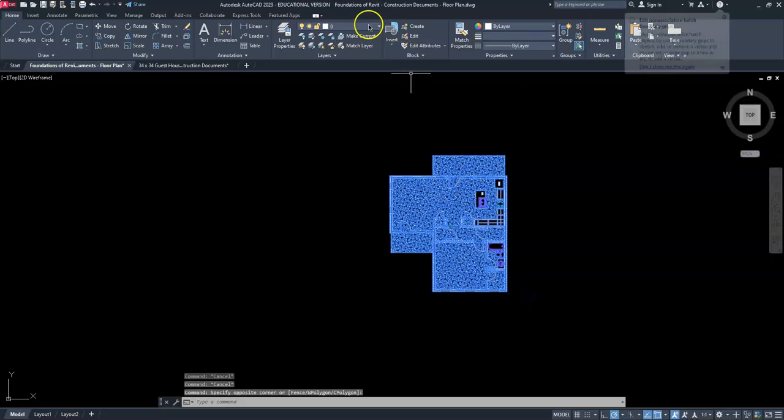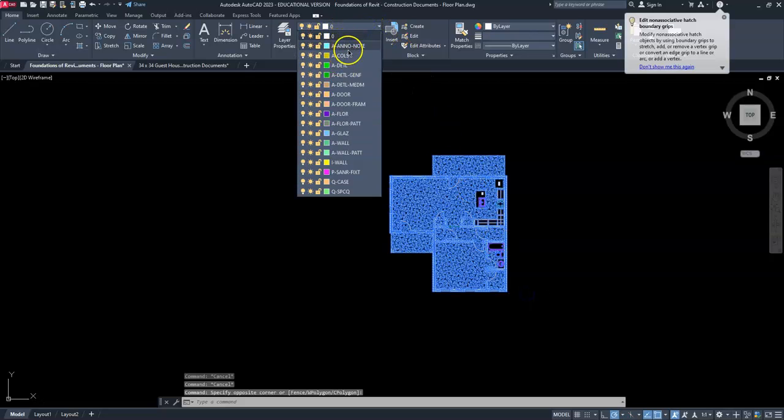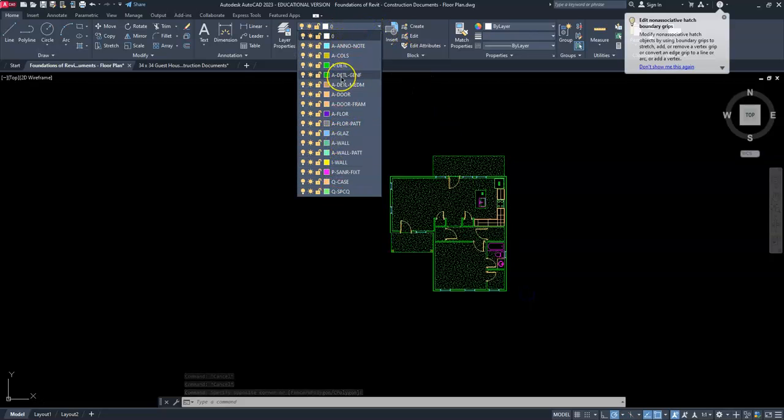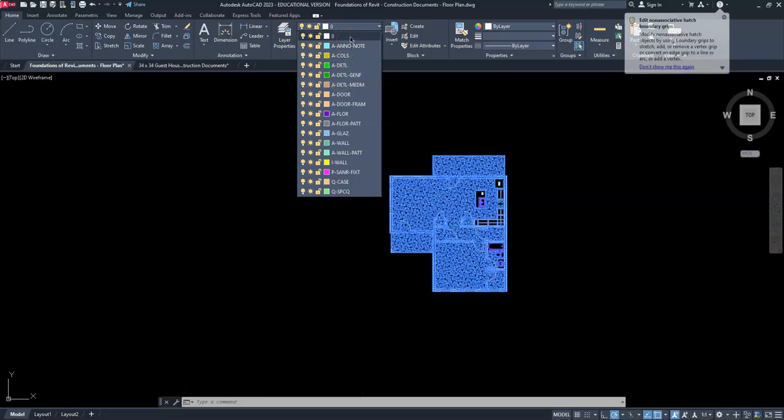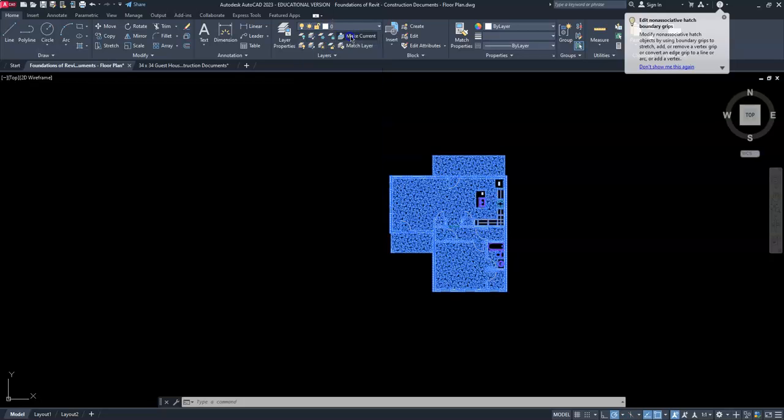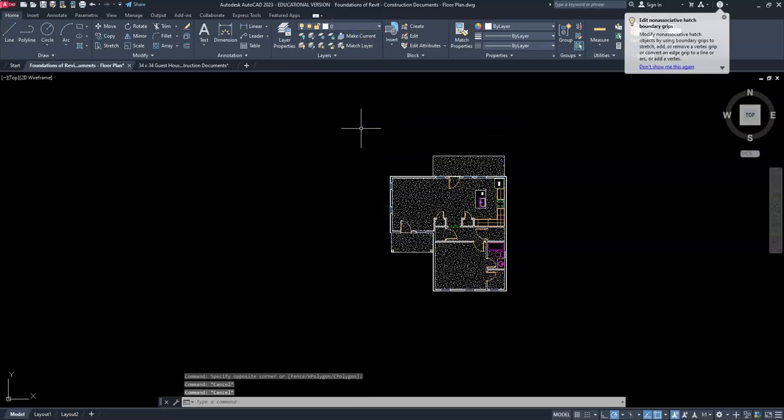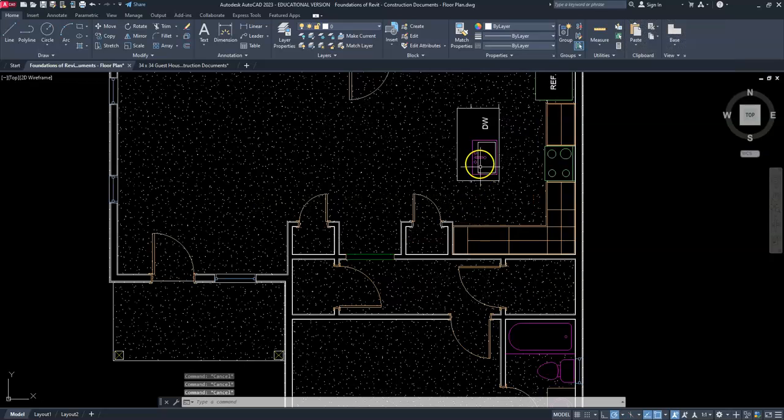So we're going to change everything to 0 so that we're not transposing and copying in all of these extra layers into our template file. So we're going to keep our file light. We'll change everything to 0. Now some lines changed, some lines didn't. That's not a problem. These are joined, grouped together sets of elements, but the layer is still 0.